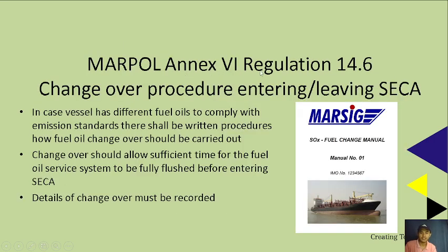MARPOL Annex 6 Regulation 14.6, changeover procedure when entering or leaving SECA areas. In case a vessel has different fuel oils to comply with emission standards, there shall be written procedures on how fuel oil changeover should be carried out. Changeover should allow sufficient time for the fuel oil service system to be fully flushed before entering SECA areas.